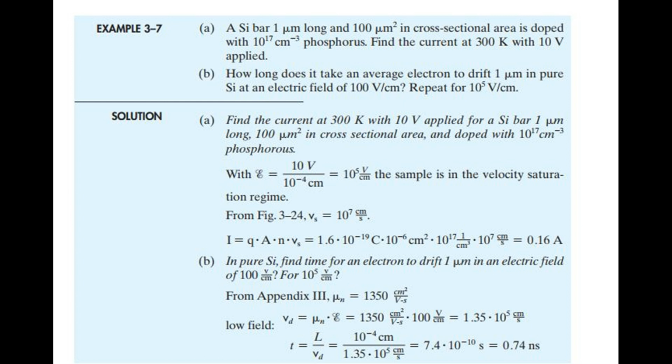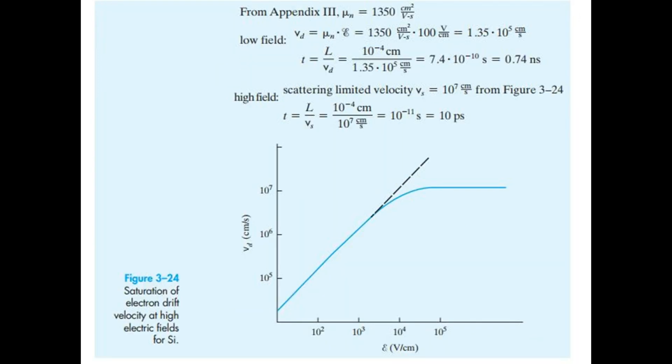High field effects. One assumption implied in the derivation of Eq 3-39 was that Ohm's law is valid in the carrier drift processes. That is, it was assumed that the drift current is proportional to the electric field and that the proportionality constant, σ, is not a function of field. This assumption is valid over a wide range of fields. However, large electric fields, on the order of 10^3 V/cm, can cause the drift velocity and therefore the current J equals qnvd to exhibit a sublinear dependence on the electric field.